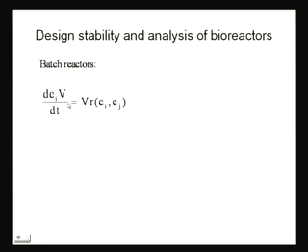Fine. Now if V is a constant, and it is going to be a constant if it's a liquid phase reaction, because liquid phase reactions typically don't change volume much. Even if they change because of molar increase, it's not appreciable. So if volume is a constant, then you can take it out of the differential and cancel it, and you will get dC/dt equals r of C.